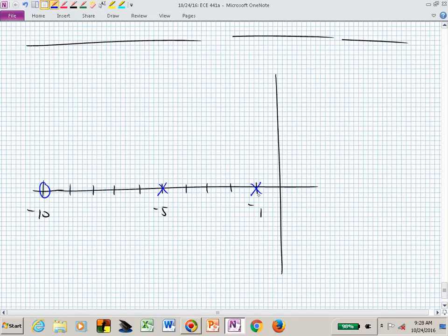That's where we started, and we started moving as we increased the gain. That pole went to the right, and this pole went to the left. And they met somewhere between. We know that they met somewhere between 2.5 and 4 because that's the first value of k that we checked, k equal to 1/2.